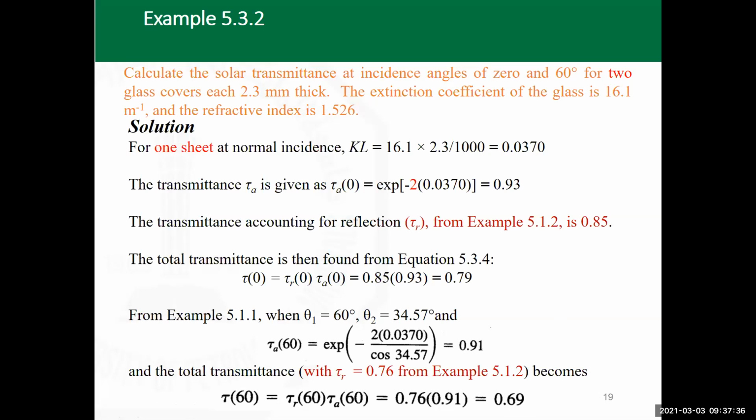Some of them are coming with evacuation, like vacuum inside, like the evacuated tubes, or as probably mentioned before, the evacuated flat plate collectors, which eliminate totally the effect of convection as well as conduction losses, and the greenhouse effect, or the low emissivity of a selective surface, is going to take care of reducing the radiation losses as well. So these are collectors that are being utilized to minimize the losses to the surroundings so that they can heat the fluid inside to much higher temperatures.